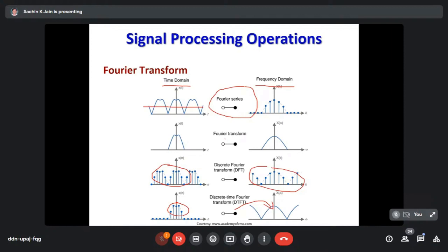For example, we use radix 2, radix 4 concepts. It is an algorithm or mechanism to compute discrete Fourier transform in a very rapid manner. Okay, and it is well suited for digital implementations. So that's the difference between DFT and FFT. So be careful when you are using these terms synonymously in your literature. They are not the same. One is a technique or a tool, whereas another is a concept. For example, DFT translates a discrete time domain signal into a discrete Fourier, frequency domain signal, right?